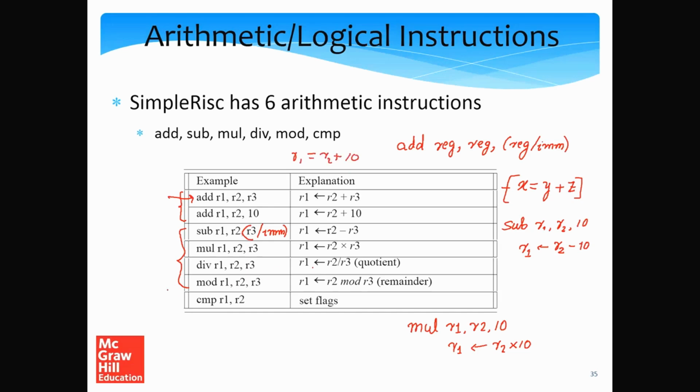So now let's take a look at the compare instruction, which is actually very interesting because it is different. So we typically don't write compare instructions of this type in a high level language. So in this case, what we do is that we pretty much subtract R1 minus R2. If the result is equal to 0, then we can infer an equality. So we set flags.e, which is the equality flag, to 1. If R1 minus R2 is greater than 0,